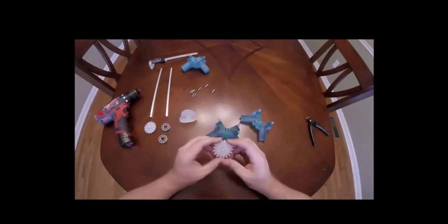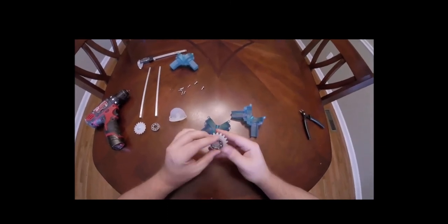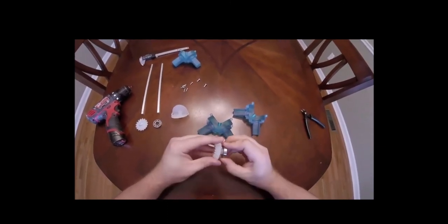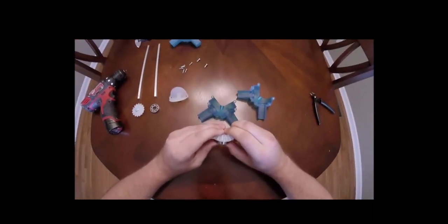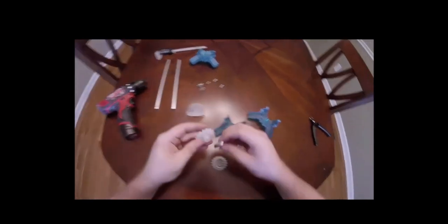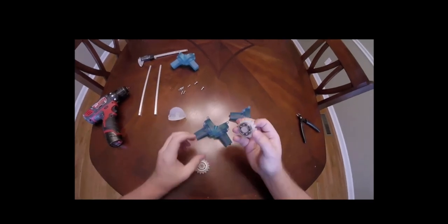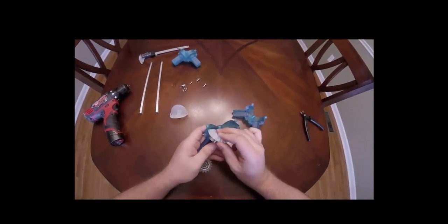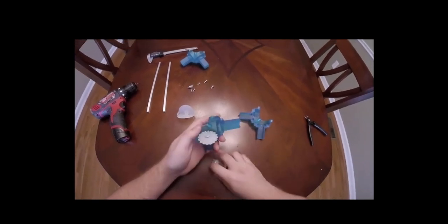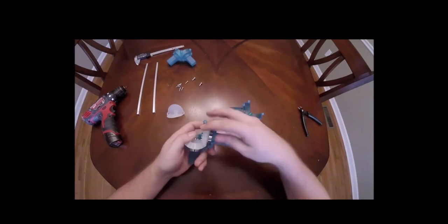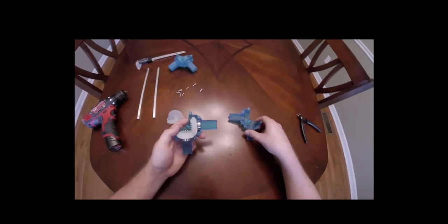So a couple of gears printed in Durable Resin with an interference fit to make a nice press fit into these bearings, which I've got to get aligned, and then just push these together. Same thing with this one. And these will get assembled into this gearbox. So one half here, and the other half here. So we've got the two gears assembled, and they run nicely together.